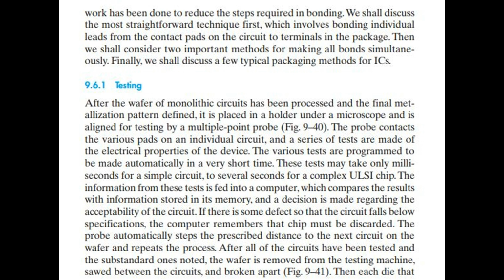The information from these tests is fed into a computer, which compares the results with information stored in its memory, and a decision is made regarding the acceptability of the circuit. If there is some defect so that the circuit falls below specifications, the computer remembers that chip must be discarded. The probe automatically steps the prescribed distance to the next circuit on the wafer and repeats the process.